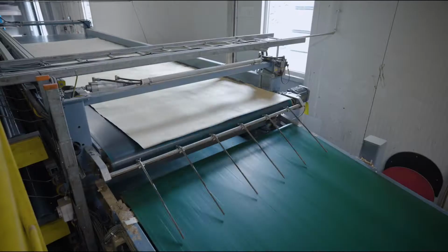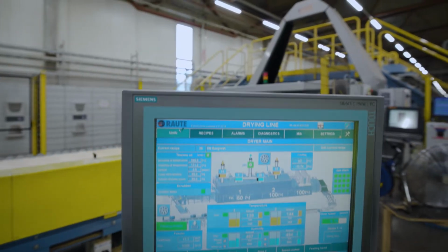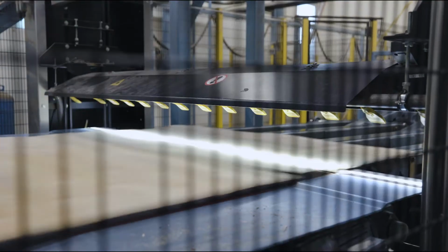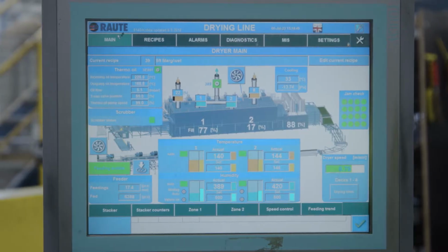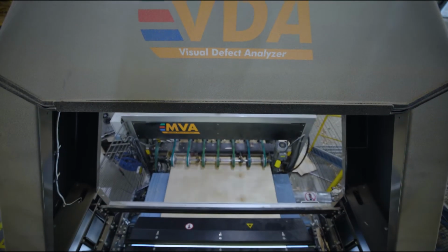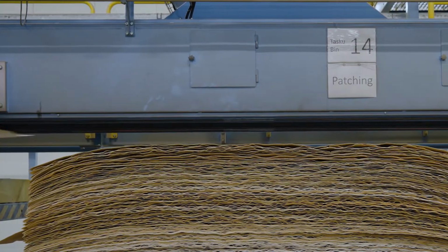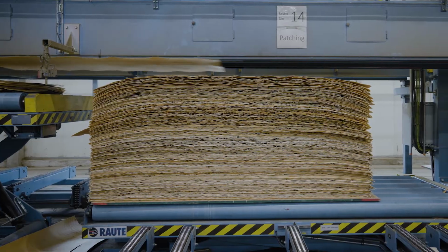Modern veneer grading solutions include analyzers, such as visual, moisture, or strength analyzers, to grade each veneer sheet and determine its structural properties before it is used in plywood production. Analyzers determine if sheets should be patched, composed, or scarf jointed before use in plywood manufacturing.